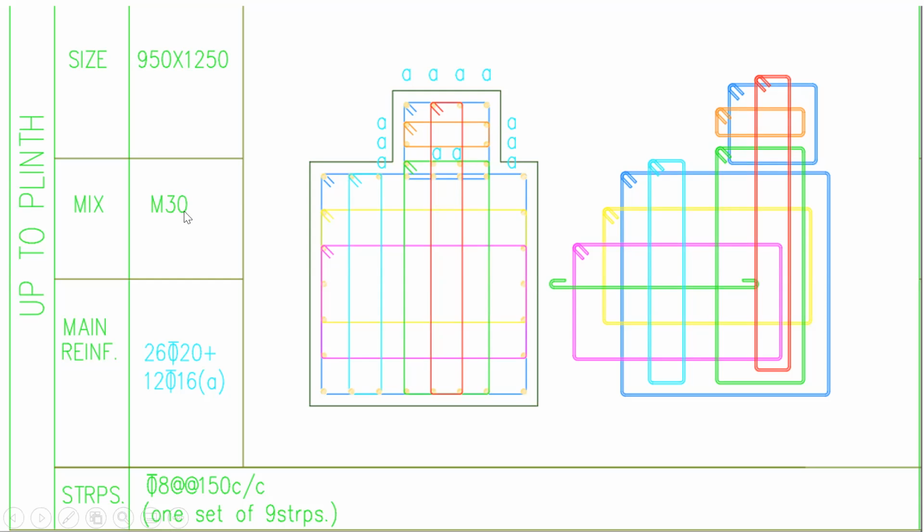One is for the footing, the beam and the first slab, let us say M25, whereas for the column we'll try to use M30 grade of concrete. The logic behind this is, since the column is a compression member and concrete is strong in compression, we are going to use M30 grade in the column. Again, it depends. It's up to the structural engineer what kind of grade he has to specify. Fine.